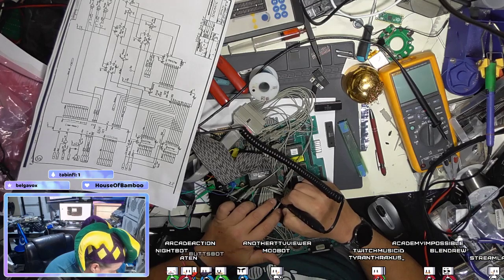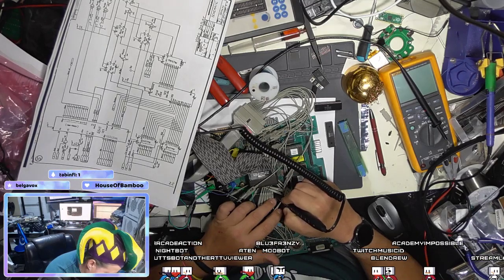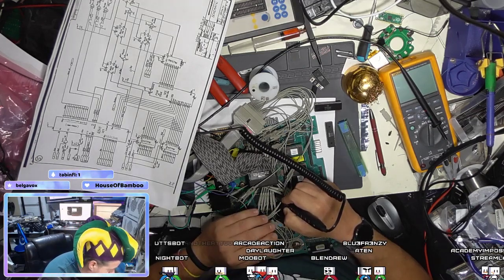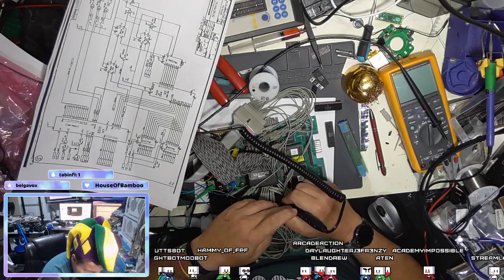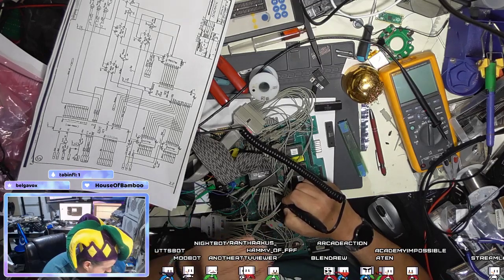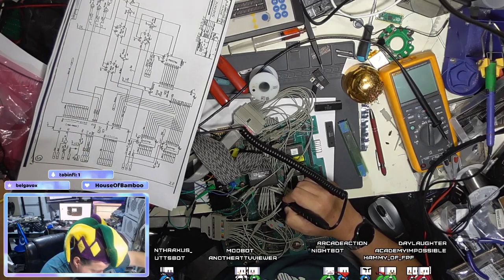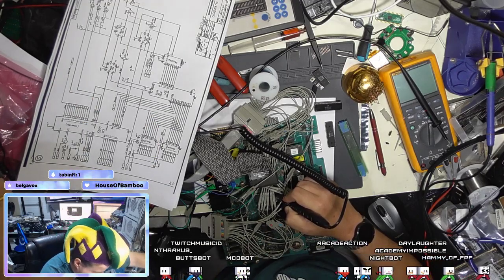25. Chip select. Alright, so I'm going to do a reset. If this one never goes low, this chip is never going to do anything with the signals. So I'm going to turn it off. It's definitely going to be low when it's off, so I'm going to turn it on.